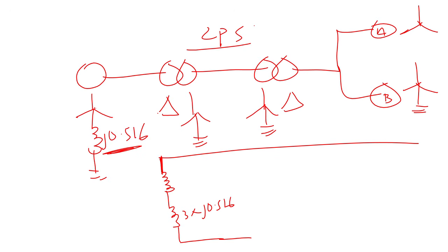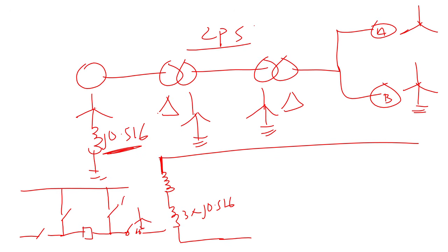Now the transformer, we have learned that we are going to use this basic diagram, a diagram like this, where this is for the star, this part is for the delta, and then the reactance of the transformer here, this part for the delta, and this part for star. So if it's star grounded, I'm going to close this. This is for delta, this is for delta, this is for star grounded, and this is looking at the primary side, and this is the secondary side.